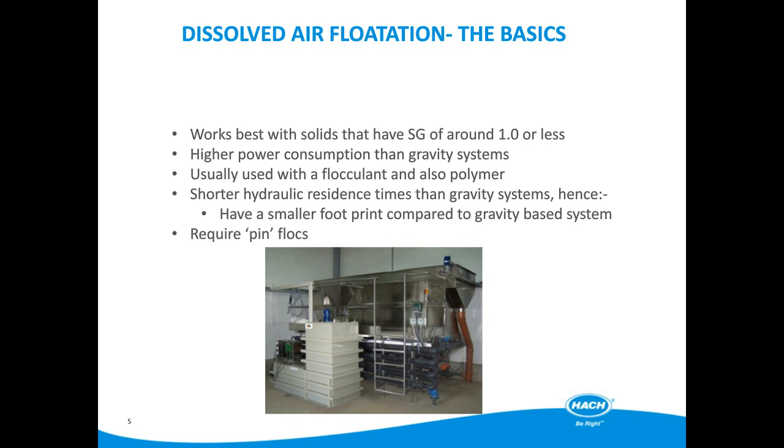It's merely an enhanced solids removal process which works best with solids that have specific gravities of around 1 or less, as these would be difficult to remove in a normal gravity-driven settlement tank. DAFs have a much smaller footprint than a conventional settling process due to the short retention times of the process.